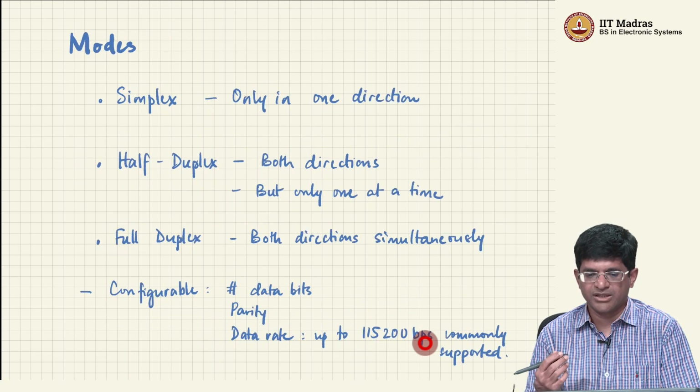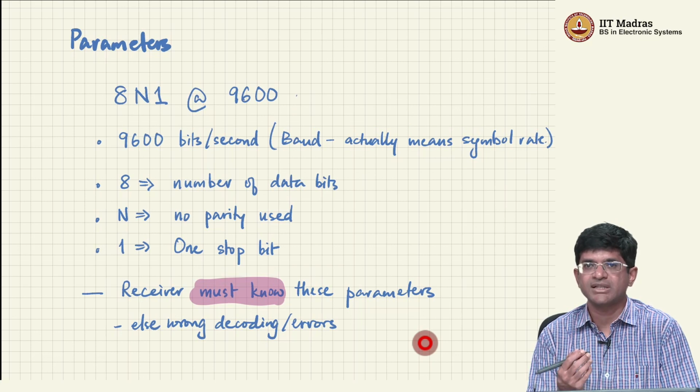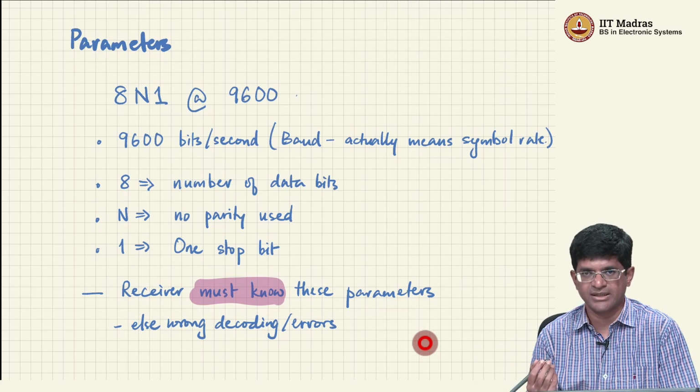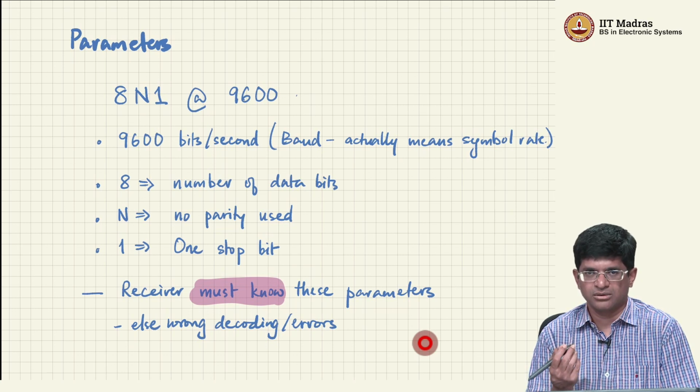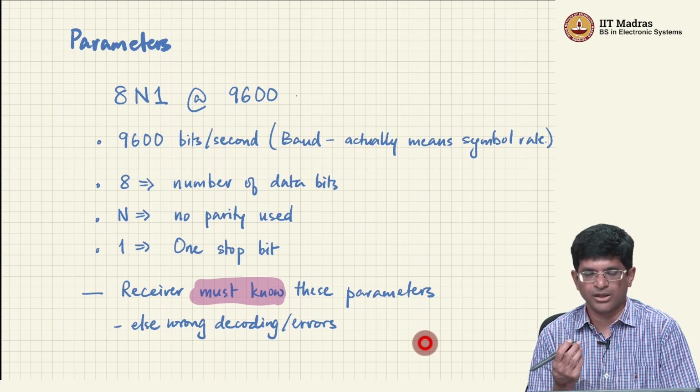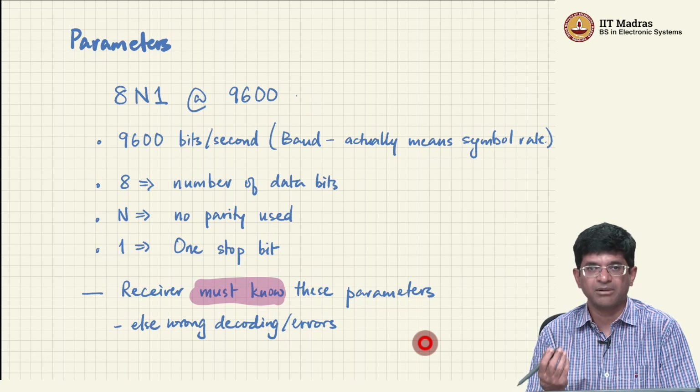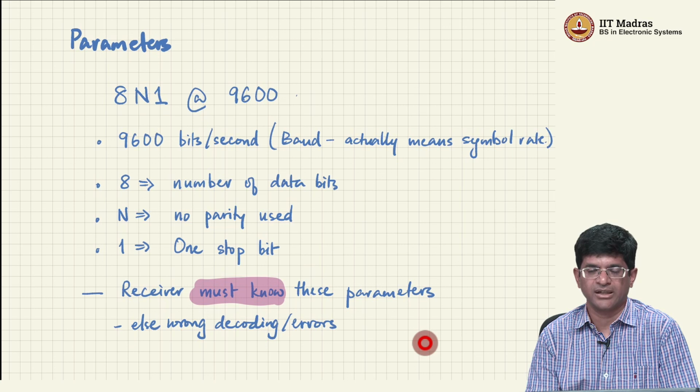So there are different modes in which you can basically use the UART. By the way, this entire protocol is what's called the UART, Universal Asynchronous Receiver Transmitter. I have talked about the transmitter and also what the receiver does, right? There is also a version called the USART, the Universal Synchronous Asynchronous Receiver Transmitter, which has some extra logic in it to allow for some kind of synchronous transmission. For the most part, it is not very common. It is not the usual version of the protocol that's used, right? The UART is what is commonly used because of its simplicity. But what you actually have physically might be a USART, which is sort of a superset of what the UART can do and can still communicate with UART kind of peripherals.